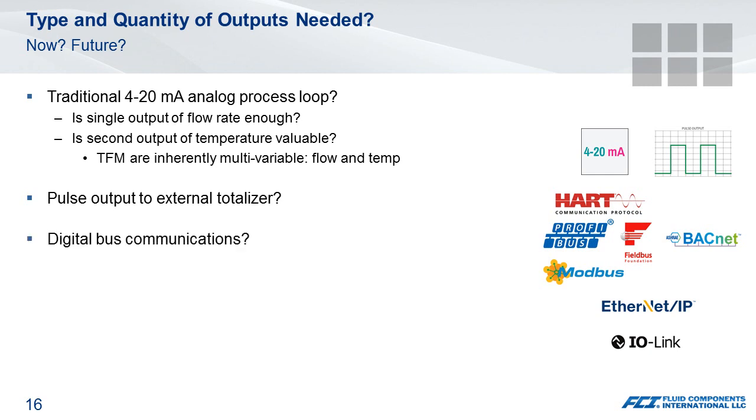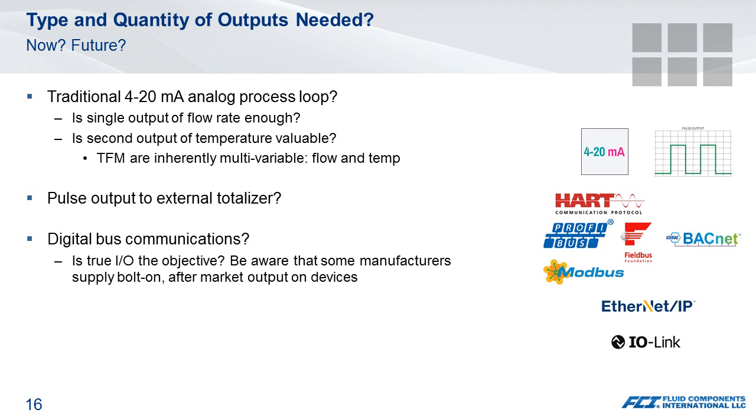There are manufacturers out there that offer it both ways, strictly an output, and others that are true I/O. And unless you specify that on your documents, you may not know which it is and get surprised. Further than that, is the device registered by one of these bus organizations? Is that important to your installation, that it be certified, tested, and blessed by the bus communication standard committee? If that's so, be sure you specify that up front.